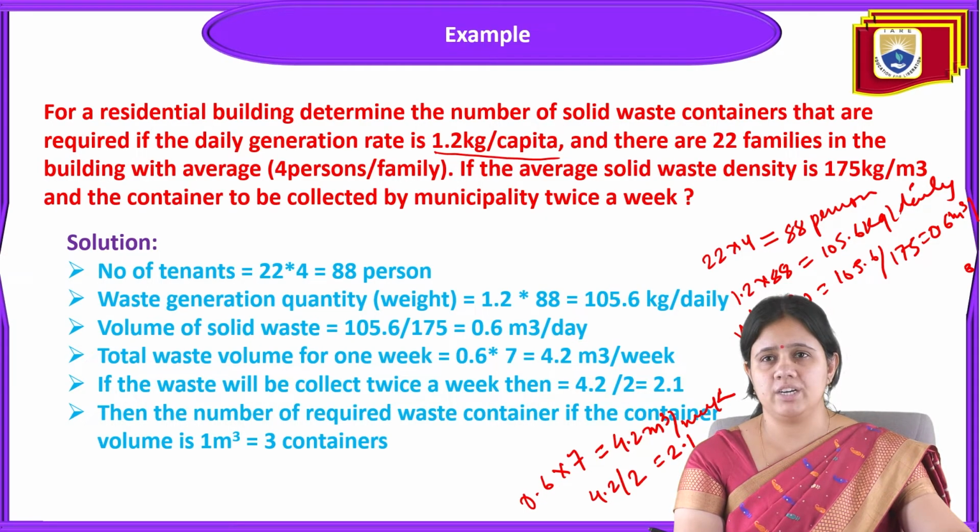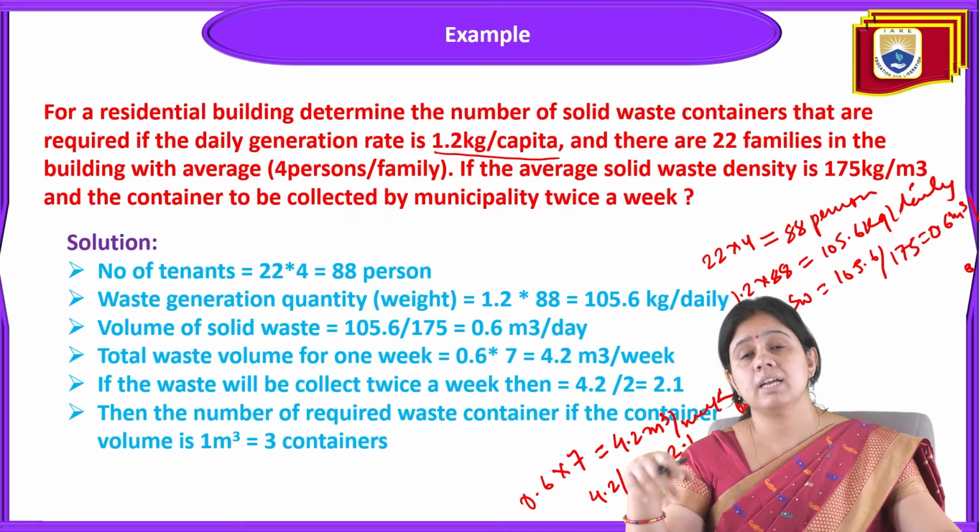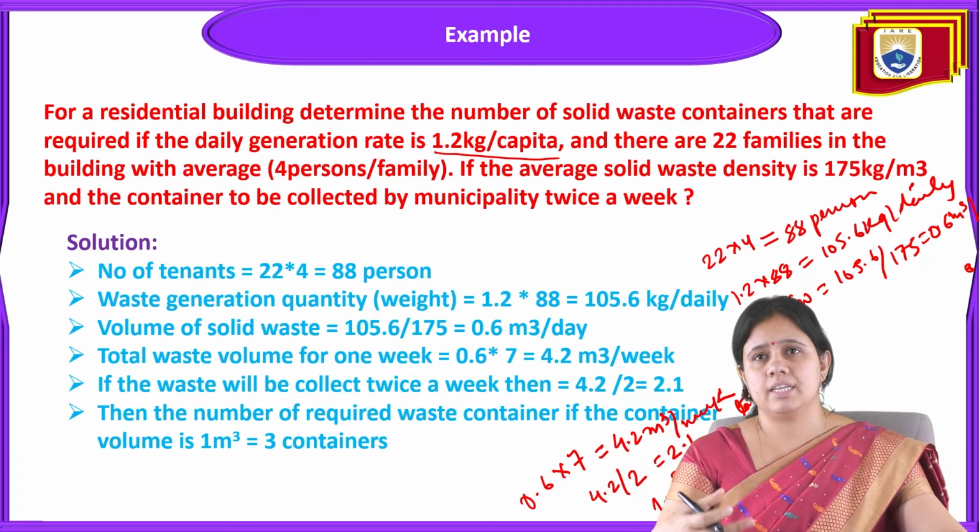Then the number of required waste containers, if the container volume is 1 meter cube, is 3 containers for collection of waste. So this problem has calculated how many containers are required if the waste collection by the municipality is twice a week and there are 22 families, with 4 members in each family. So for this type of waste collection system, we need 3 containers.